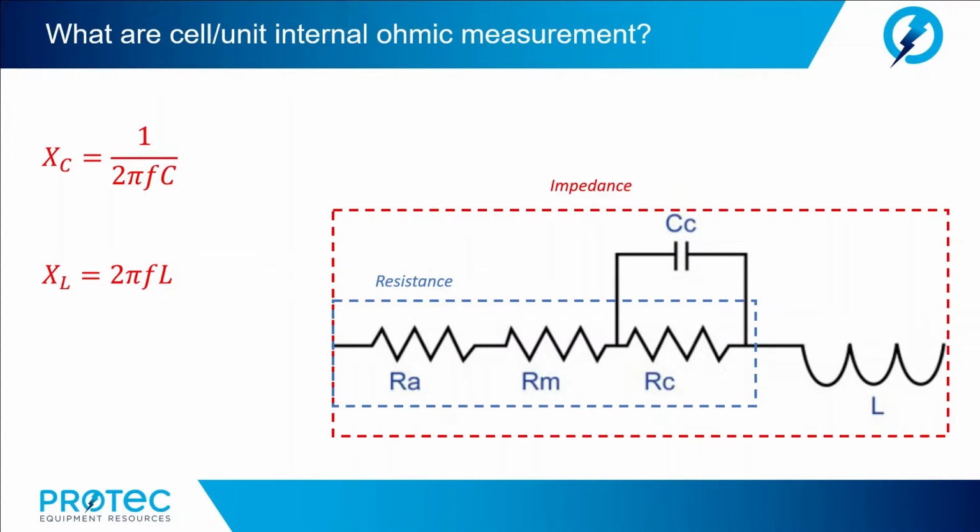Manufacturers using proprietary methods and applying different frequencies and magnitudes for their signals have developed a diversity of measurement devices. This diversity in test signals, coupled with the three different types of ohmic measurement techniques, impedance, conductance, and/or resistance, make it impossible to always get the same ohmic measurement for a cell with different ohmic measurement devices.